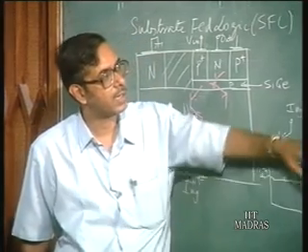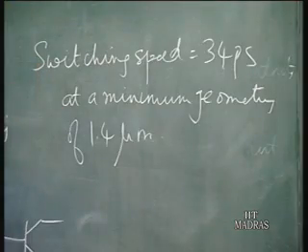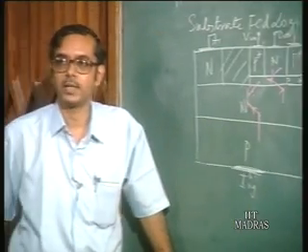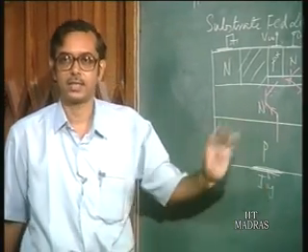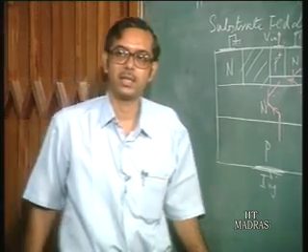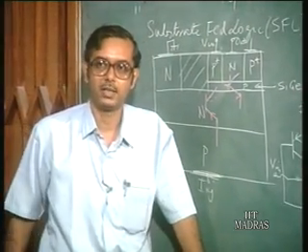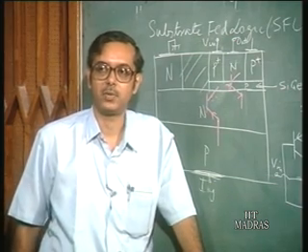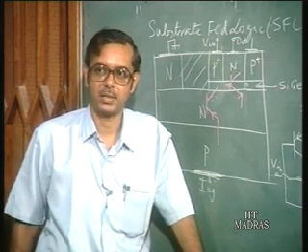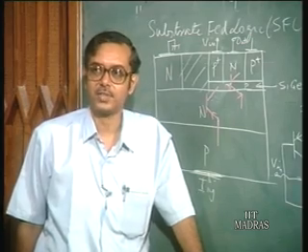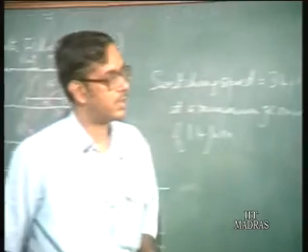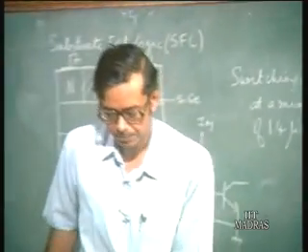One way to do it is heterojunction I²L, and the delays being talked of are quite remarkable, just 34 picoseconds, which would really make it a very high speed logic family, although we don't really call I²L a high speed logic family. That is why I wanted to introduce this to you, and this is very recent work.